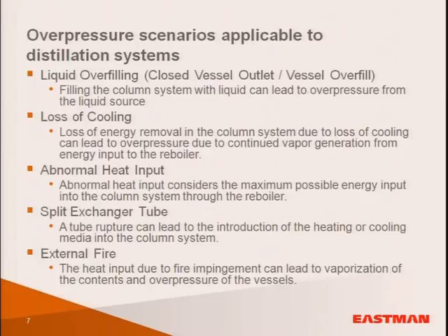Split exchanger tube is a concern if we have a tube rupture that leads to introducing our heating or cooling media into the column system. And of course, we can have external fire impingement on the outside of the column, and that can lead to vaporization of the contents and subsequent overpressure.